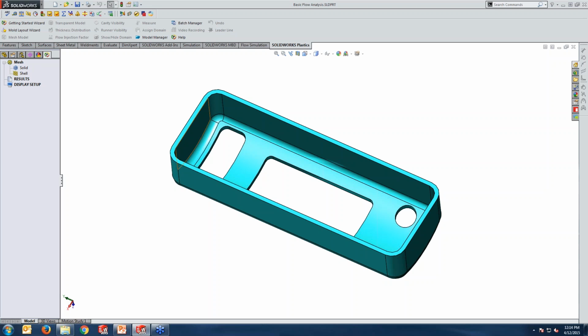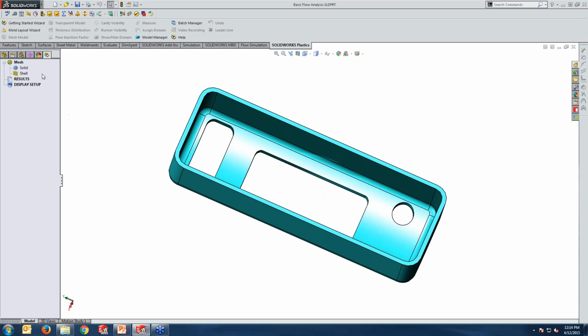Those triangles are simply sharing points when they are attached together, and these are nodes, and these are exactly where we are doing our calculation. So we are going to explain this a bit more while we do the mesh, but just letting you know, in order to conduct any sort of simulation, you have to convert the CAD geometry to the network of elements, and all the calculations are happening within the element side.